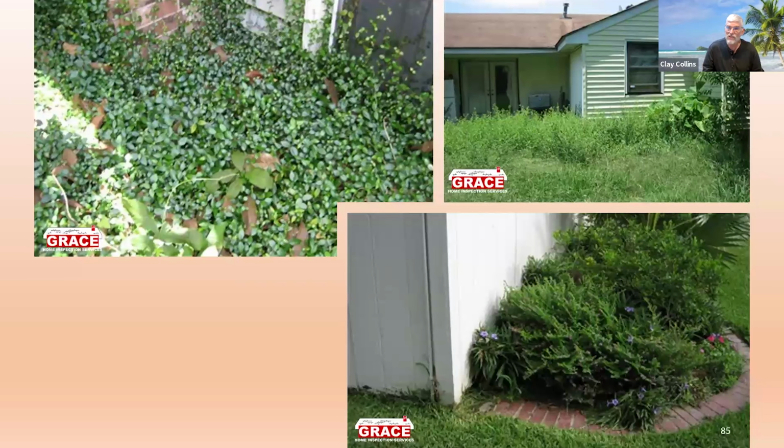I think we've all inspected a home or two like that. And you have to say, I don't know how it's going to drain, if you're not there to watch it until they do their landscaping, until they do anything. So I report this as a deficiency and say you should expect that there's going to be poor drainage.